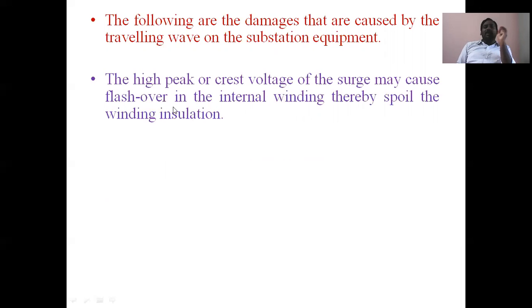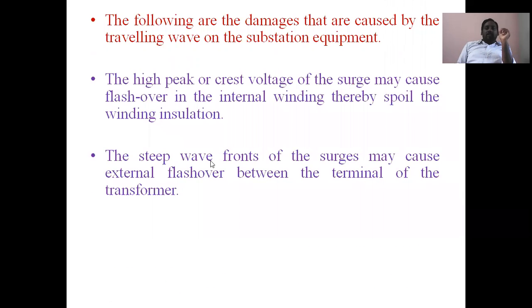Flashover can exist due to lightning voltage. Second, the steep wave fronts, meaning high magnitudes of voltages, of surges may cause external flashover between terminals of the transformer.